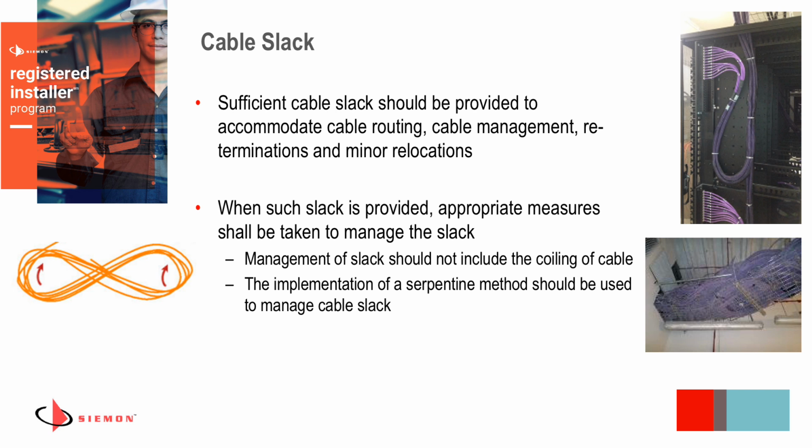You don't want to coil cables up. If you have additional slack, maybe you want to leave it in a basket tray. It's better to do a figure-8 than it is to do a cable coil, which can have negative performance effects. So consider that if you have any longer lengths of cable that you need to store slack for.